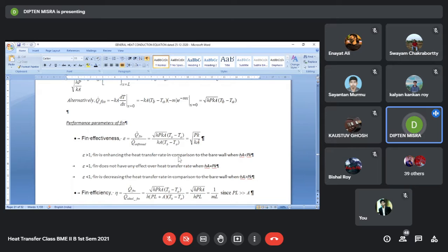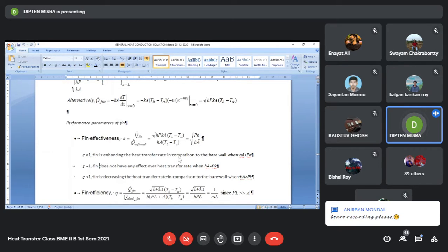Now, if we want to promote this heat transfer, then what we can do is think of attaching a fin. Now, the question is, if we have two different fluids on two different sides, having two different values of H, H1 and H2, what you will see is that the fins are attached many a time on one side, not on both sides.